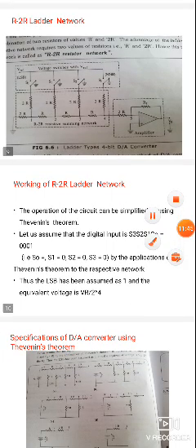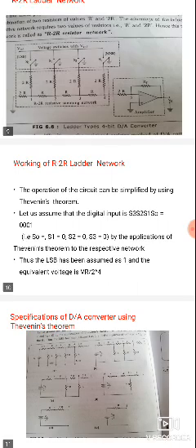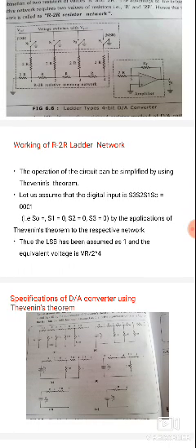Here the op-amp uses negative feedback. Feedback is nothing but a direct connection from output to input, using the RF feedback. Here we are using a resistor for the feedback purpose. The feedback resistor is called RF. This is about the designing of the circuit. The design is simple. It uses only two resistor combinations and switches, and only one op-amp is used.